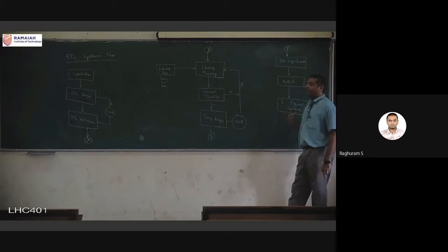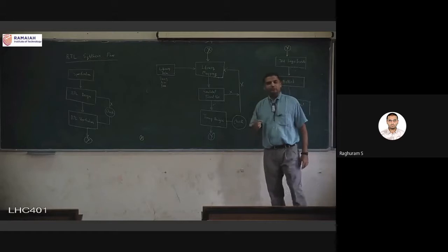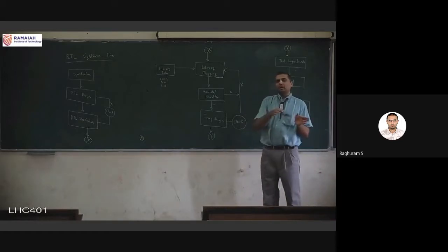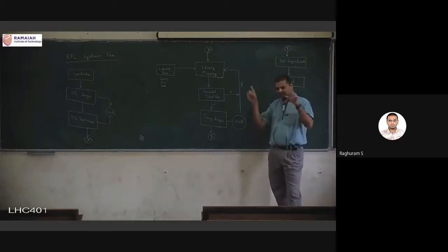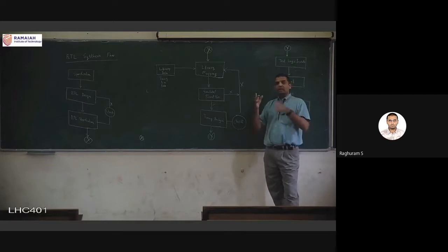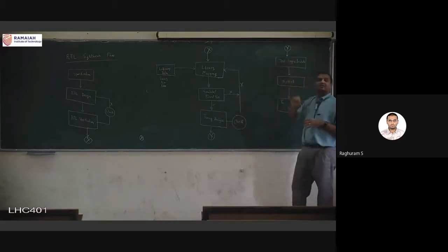Okay. And what is the meaning of this test logic? Every gate in the design can operate in normal mode or in test mode. And there will be a pin as part of the inputs to decide whether the gate is operating in normal mode or test mode. And if it is in test mode, that means that the inputs of the gate are coming from a different source. Where is it coming from? That is this test logic.